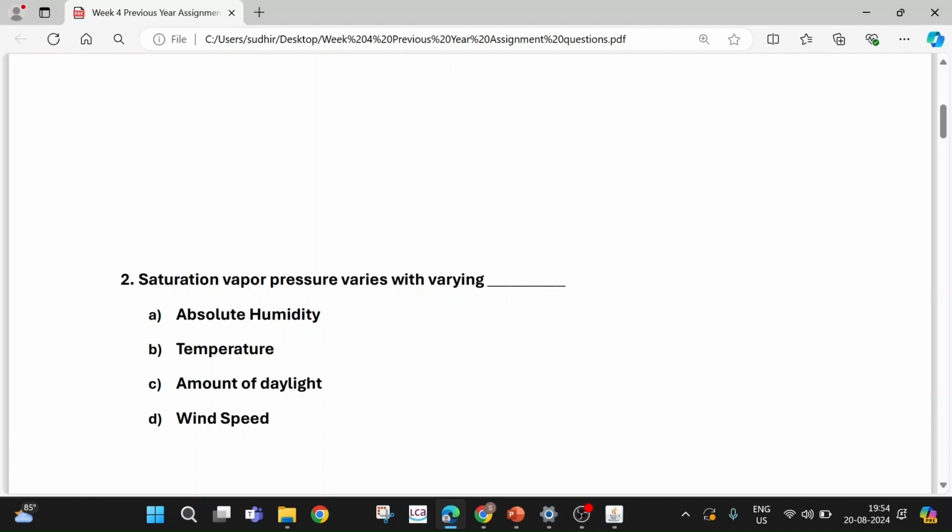In power plants it is mainly used. Whenever you use the steam tables, the properties of water at different temperatures are mentioned. Like if the power plant has heated the water and made steam out of it at a temperature of 340 degrees Celsius or 200 degrees Celsius, then at that particular temperature what will be the other properties of the steam, like entropy, enthalpy, saturation temperature, saturation pressure, or the specific volume, and what will be the changes in the density.